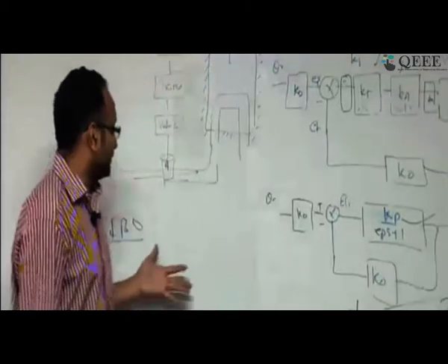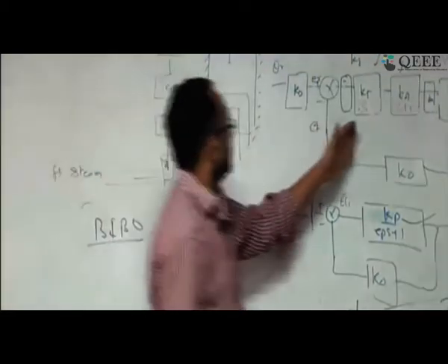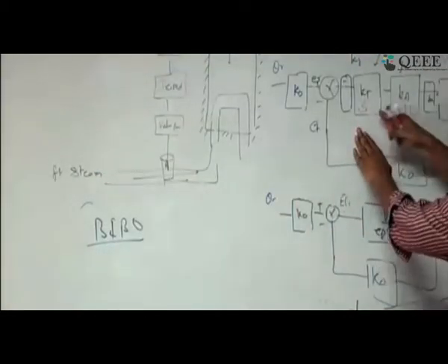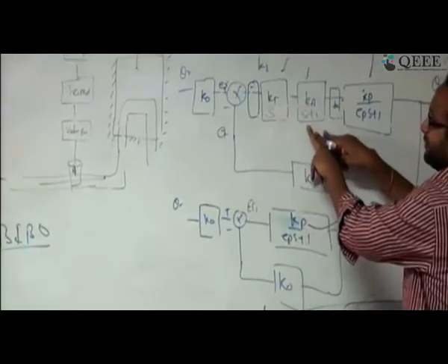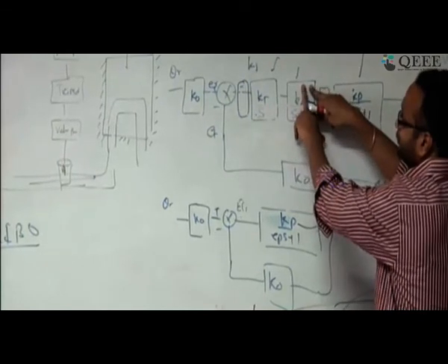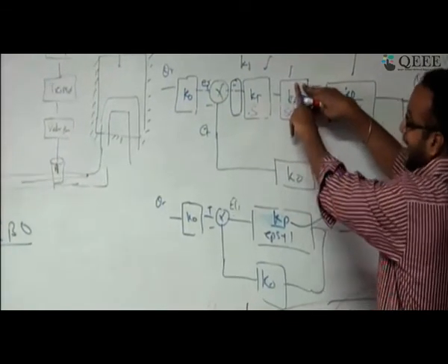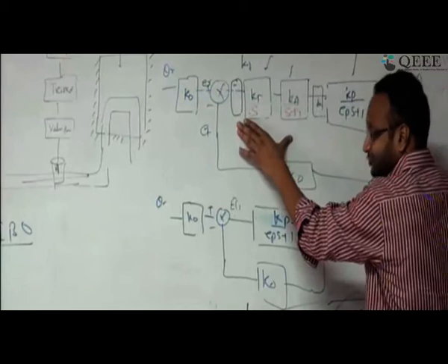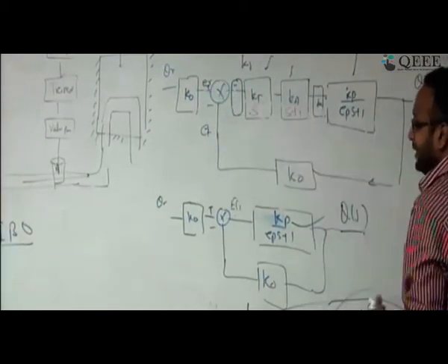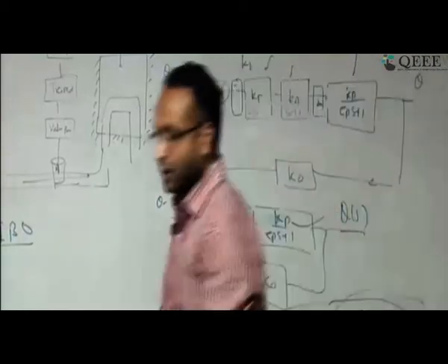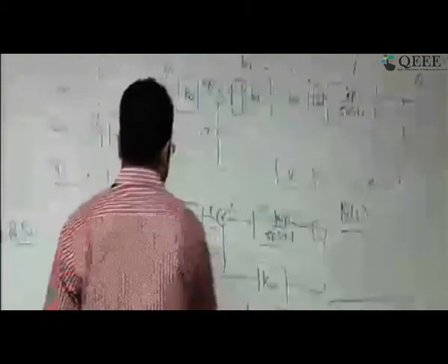So what has been observed is that in reality you can make the system this way, but this might lead to instability, because the assumption in the mathematical analysis that this becomes a zeroth order system is not valid. It actually becomes a higher order system, and if you keep on increasing k, the system will become unstable. And I can show you with a small example how the system will become unstable.